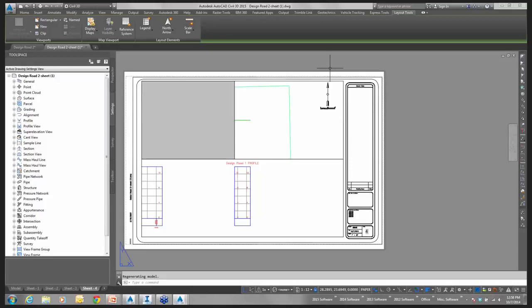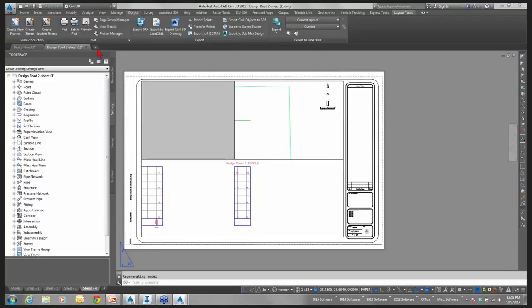So that's creating alignments and profiles in Infraworks, bringing it into Civil, bringing in solids into Civil from Infraworks, creating plan and profile sheets from Infraworks into Civil. Those capabilities, you can get to 30% complete on a project before you even won the bid. Very simple, very nice tools to use. And then once I'm done, I can actually say output, and I can export out an IMX file and take any corridors, pipe networks, surfaces, and bring those into Infraworks and complete the round tripping.